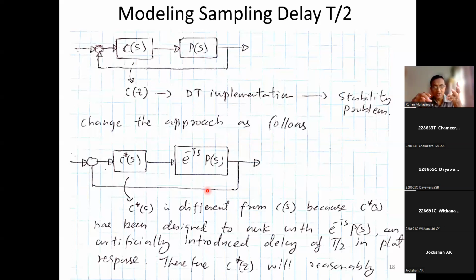And also delay comes in, right? So if you do not want to go to the discrete world and see for yourself how the delay affects the response, what you want to do is put a delay block in front of the transfer function or the sensor, and then simulate the whole thing, to figure out what sort of deteriorations are happening. There can be slight deteriorations, but then you change your sampling interval in a range and see for what sampling intervals you get better performance and for what you are not going to get any useful response.